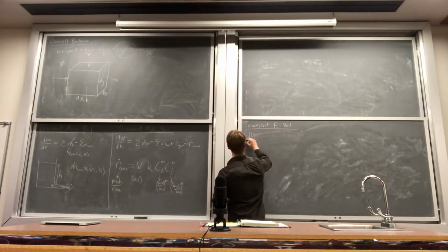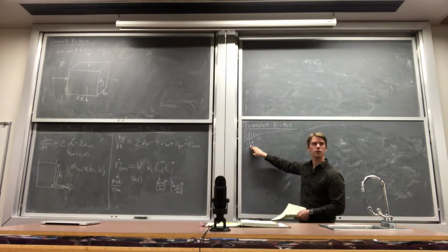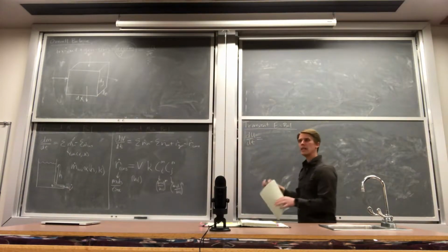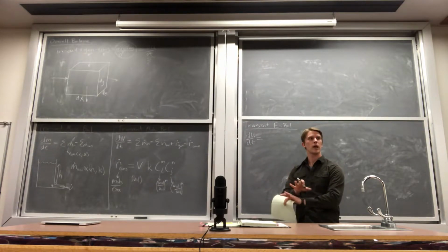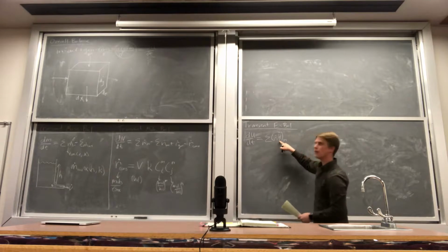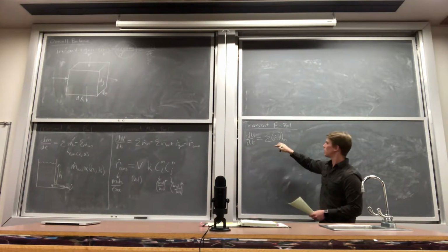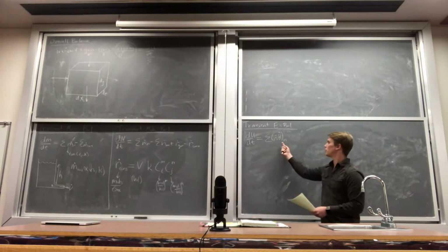So dU/dt, the total internal energy of the system, right, which is our stand-in for the total energy basically, per unit time, this is our accumulation term. All we're doing is adding up all the sources of energy in and subtracting all the sources of energy out. So we have energy entering in the form of enthalpy with the molar or mass flow rate coming into the system. Right? Sometimes this could be m dot, sometimes it's n dot. It just depends on what your units of specific enthalpy are.